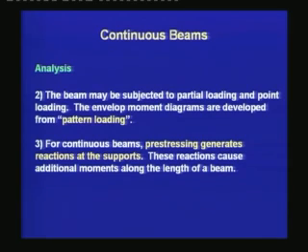Third, for continuous beams, prestressing generates reactions at the supports. These reactions cause additional moments along the length of a beam. For a simply supported beam, the concrete and steel form a self-equilibrating system. The prestressing force does not generate any reaction at the supports.